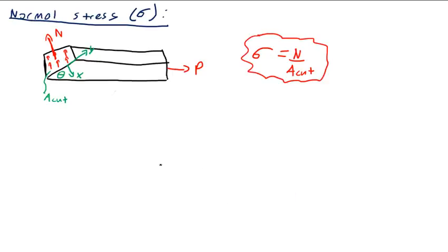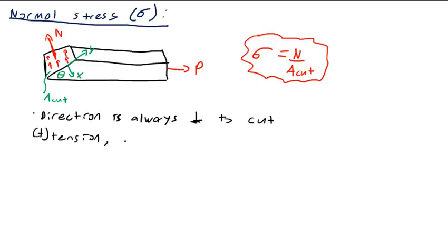Okay, a few notes. For normal stress, direction is always perpendicular to the cut. It is positive for tension, negative for compression.